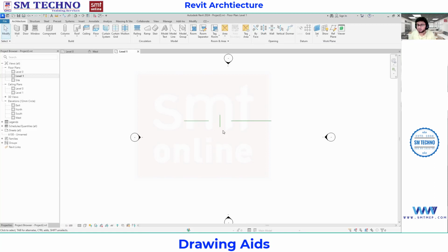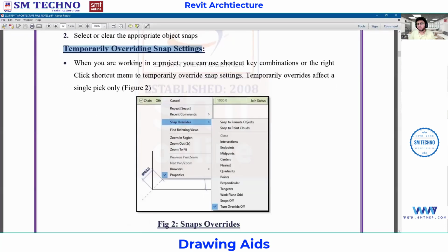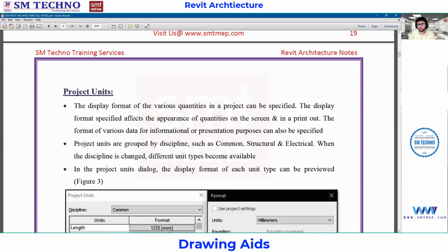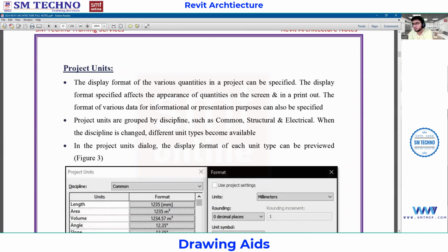Like I want to place a lighting fixture exactly at the center of the door, above the door, so you will go with this option. Or you're going to place any kind of HVAC grill between two endpoints. You need the center point of the room. In that case, we select the object, right click and go with the select between the two endpoints, and you can place it. So this is the best option we have. Whichever point you want, you can select. I hope regarding this, it's very, very clear for everyone. Any notes?